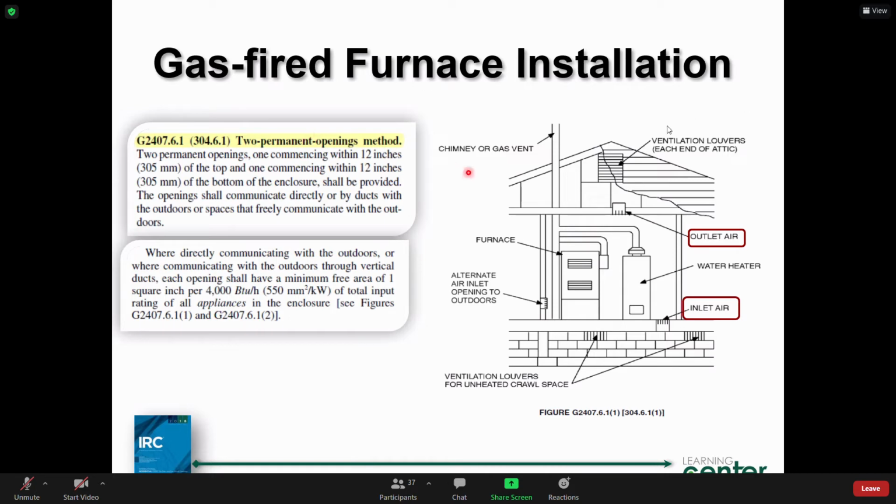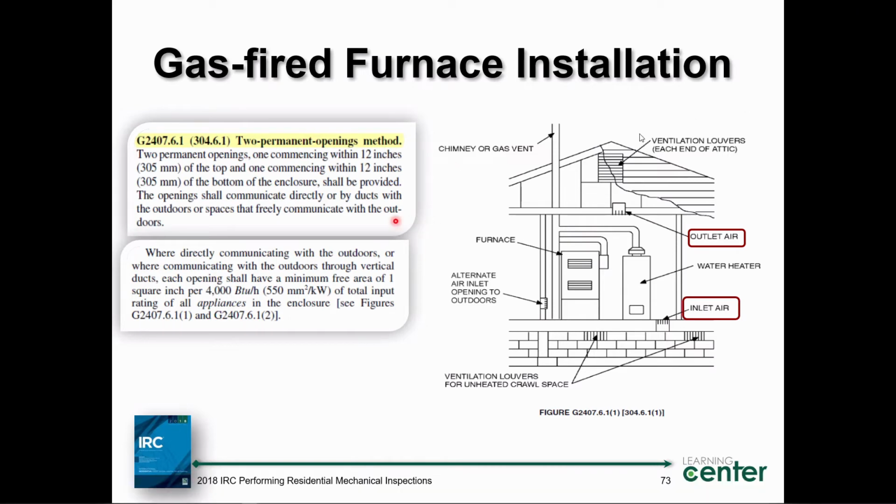Gary, go ahead. About the crawl space part, in our state, you just have to be careful whether you condition it or leave it unconditioned. This is an unconditioned crawl space, right, Francisco? This is unconditioned. You see the screens here? This is vented to the outside. So your building thermal envelope would be the floor here. This would be unconditioned crawl space. That's what we're talking about.